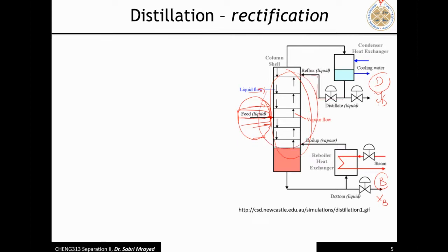And then you will be given the reflux ratio. Let's call it the reflux ratio or the reflux rate. We have two types of reflux. We have external reflux, which is R over D, and we have internal reflux, which is the ratio between the vapor and the liquid in each stage. So this is V and this is L.